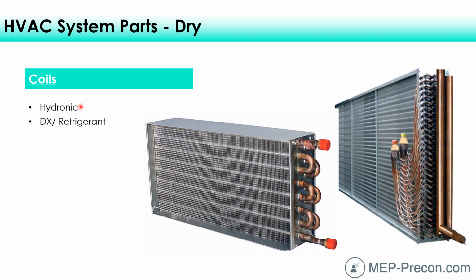And hydronic is the name that we give to HVAC water, either heating hot water or cooling water. We don't say hot water or cold water because those terms are reserved for plumbing. If you went to a pipe fitter and asked them to put up some hot water pipe or cold water pipe, they'd tell you, I'm not a plumber. I put up heating water pipe or chilled water pipe. So hydronic came around after plumbing, and so that's why we changed those terms. So heating hot water or cooling, either condenser or chilled water.